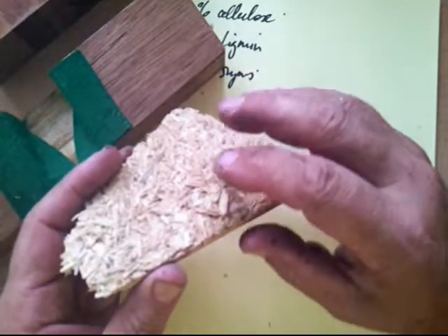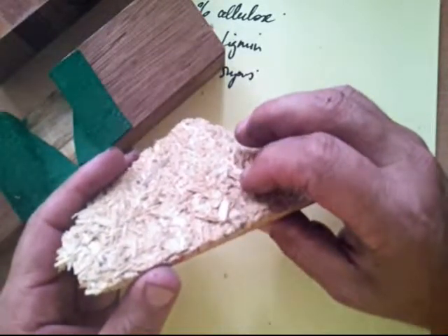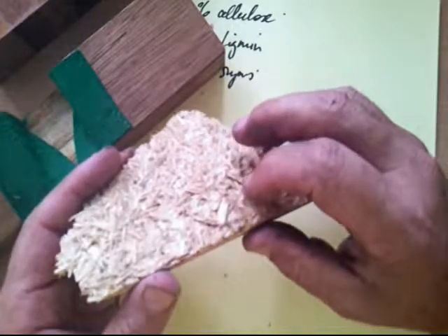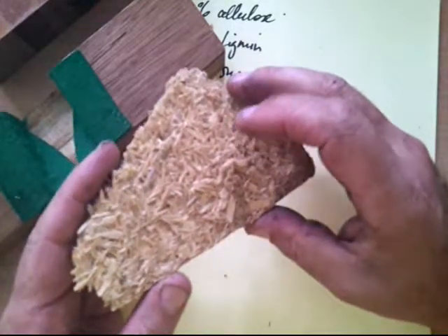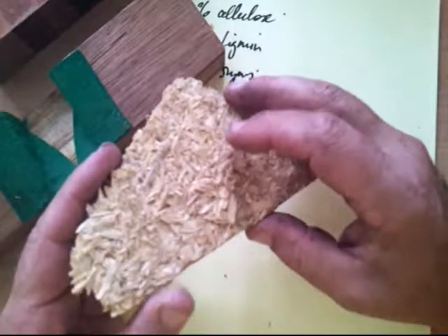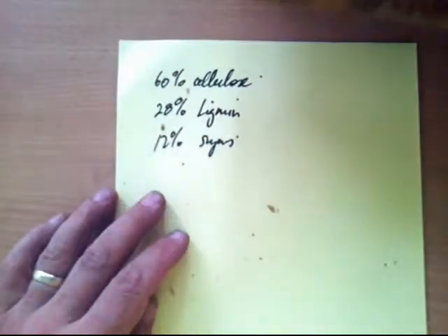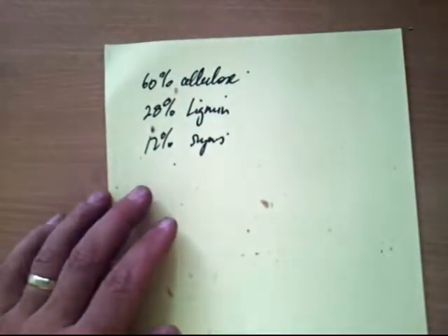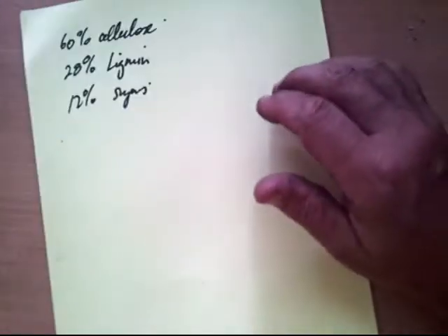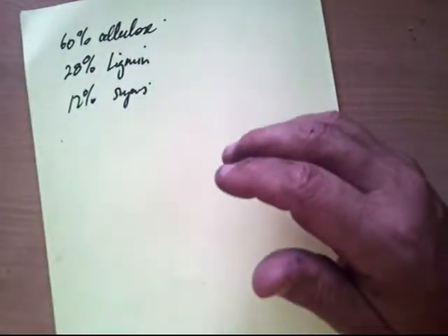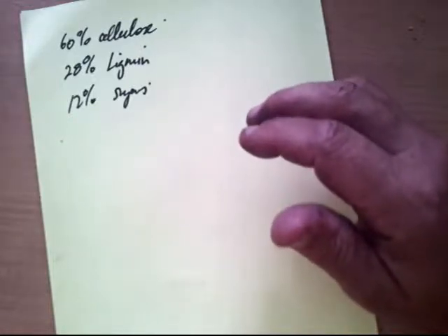Alright, particle board has another little brother and sister which I don't have an example of, called MDF, or medium density fibre board, and that's a much finer item, more dense, stronger, and a bit more water resistant than particle board, or chipboard, as this is sometimes called. So that's MDF fibre board. Again, problems with breathing the dust in when it's being cut up. It can be quite unpleasant for you.